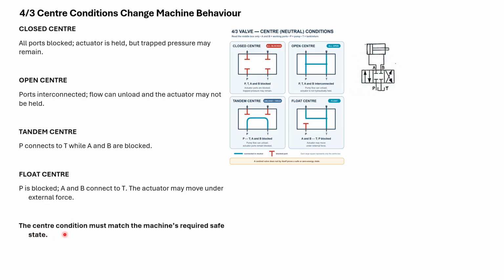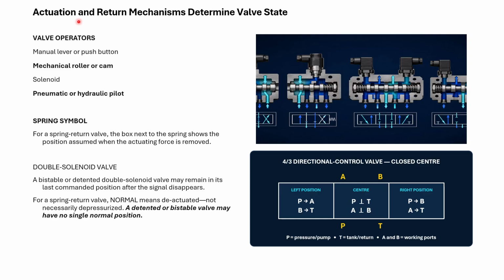The center condition must match the machine's required safe state. Actuation and return mechanism determine the valve state. Valve operators: manual lever or push button, sometimes a spring, mechanical roller or cam, solenoid, pneumatic or hydraulic pilot.